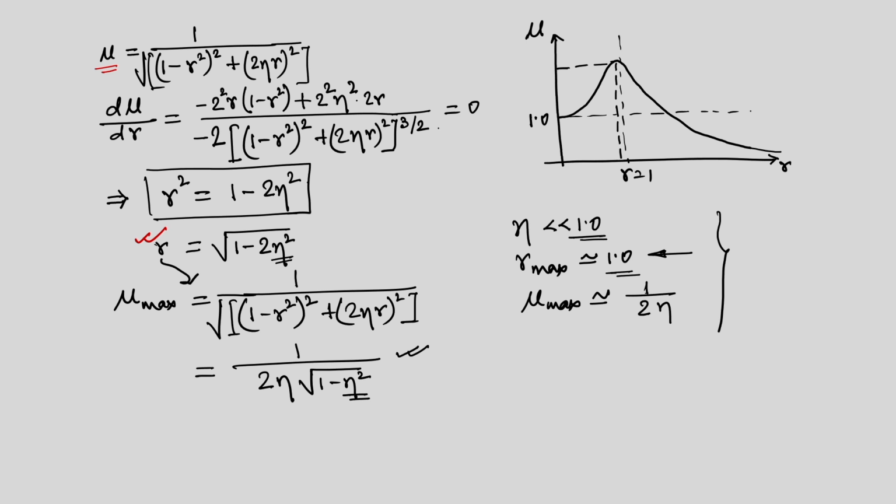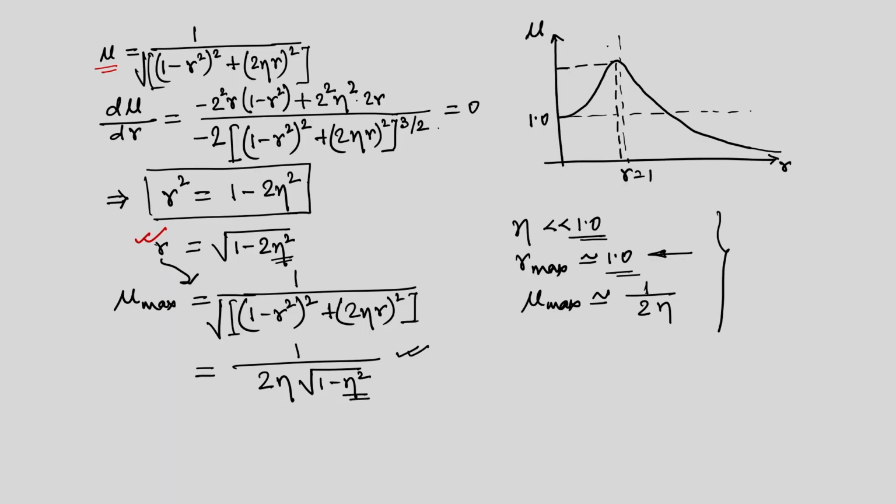Now, out of this discussion what we can conclude is that if you have a linear system, and we drive the system with a harmonic excitation, and by chance the excitation frequency matches with the natural frequency of the system, then resonance occurs. If damping is 0, then the dynamic amplification will be infinite and no structure can actually withstand that.